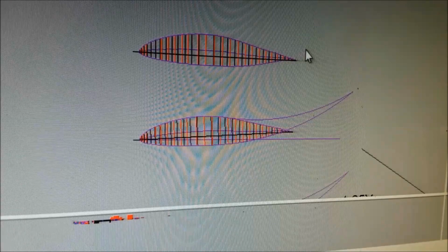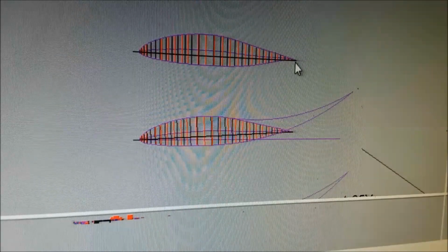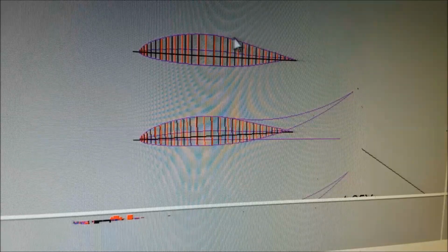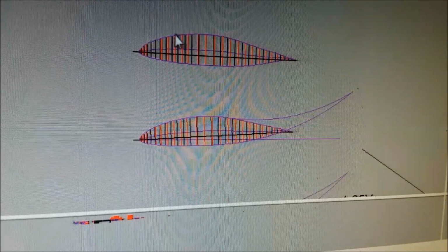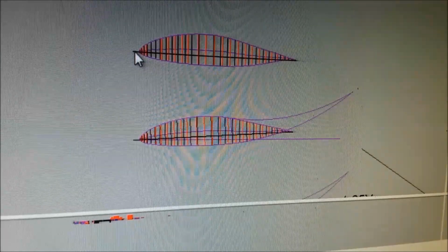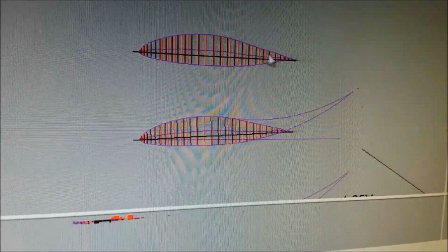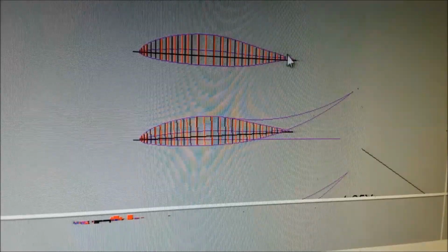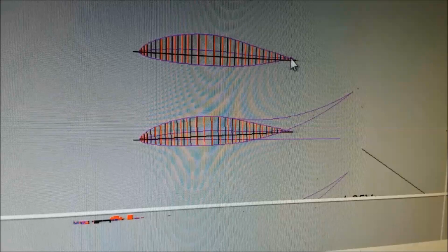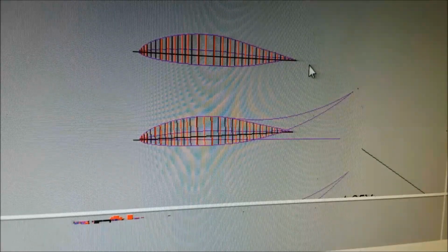It's next to Manila. But you take the foam and you just drag a wire that's heated to about 700 degrees, 15 amps probably, around 15 volts. The amps are low. And it melts that shape out. And then you wrap fiberglass around it. And to get this pointy end in the back nice and thin, you do the top all the way back as far as you want.